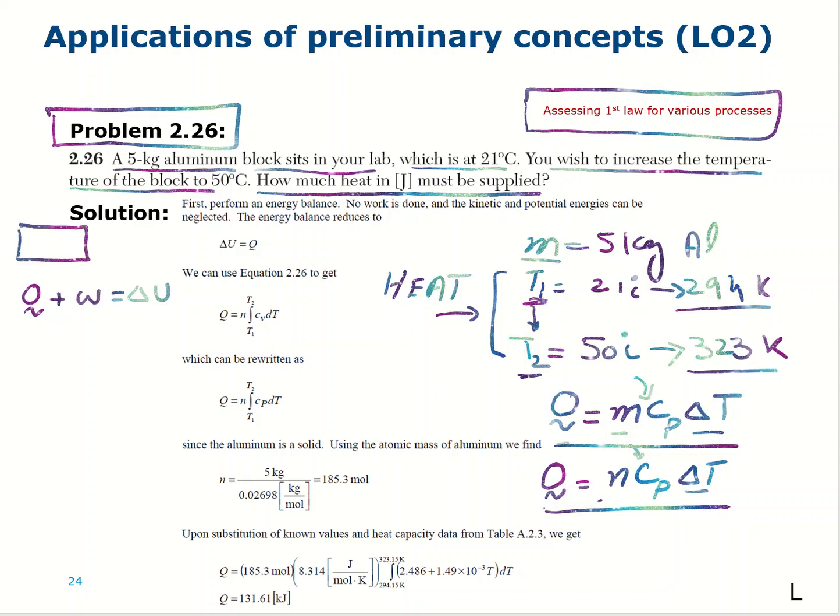Say, for example, this is a solid. It is not moving up and down, so this is not a moving piston or a rising piston-cylinder arrangement or rotating shaft arrangement. It's still solid, right? No work, it's not moving up and down. So that's why work done is 0. That means Q becomes equal to delta U for this system.